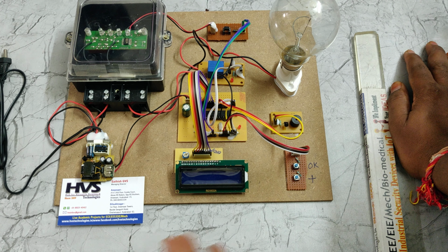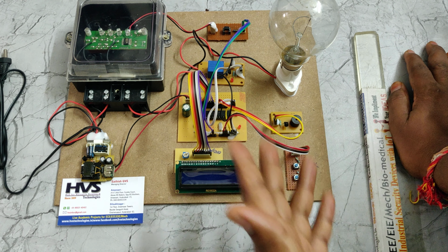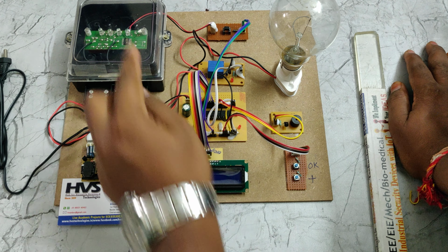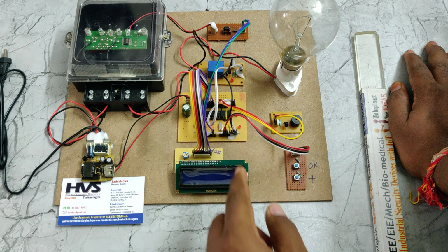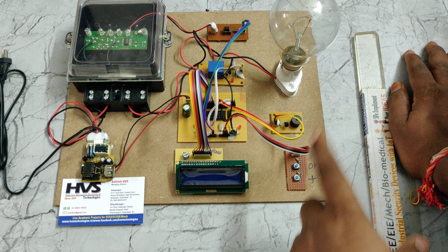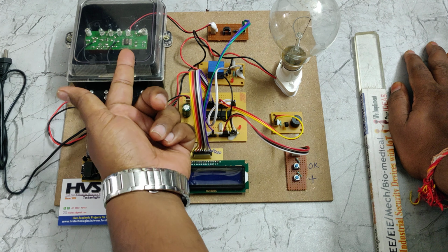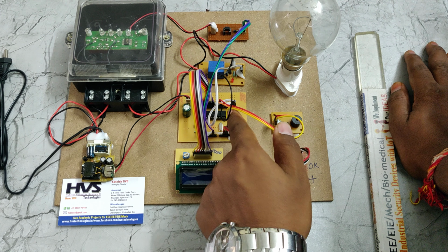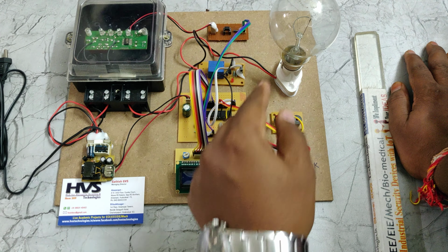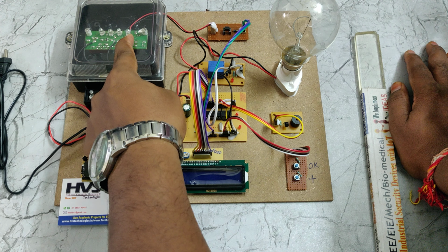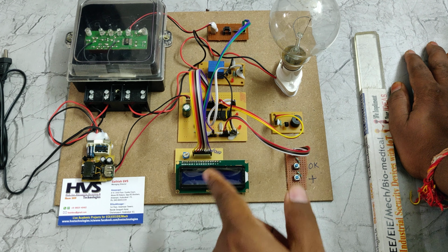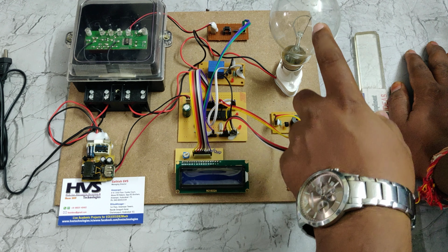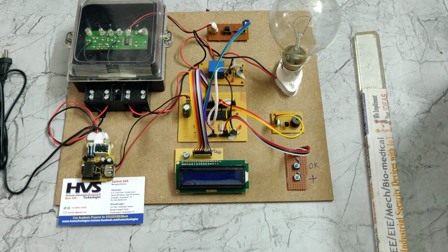So whenever the time decreases or increases, the wattage will vary. As we said, if the time duration between two blinks is 1200 milliseconds, it is considered as 1000 watts. Once the LED blinks, the microcontroller will start the timer, and it will count until the second blink comes. Between those two blinks, if it is 2400 milliseconds, then 500 watts of load is connected. So this is the calculation of the wattage.